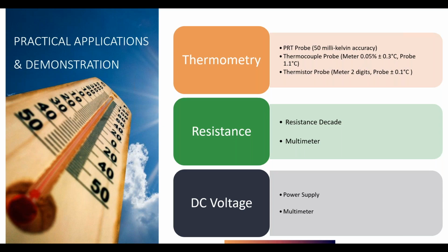Well, you know, let's take the Fluke 52, for example, because how many of you guys have a Fluke 52? I would say probably 80% of you in here have a Fluke 52. Okay, so the accuracy of a Fluke 52 meter, and I'm going to emphasize the term meter, is 0.3 degrees. Now, be honest, how many of you are aware that there's also an accuracy on the probe? Anybody aware of that? Okay, so here's where the problem starts.